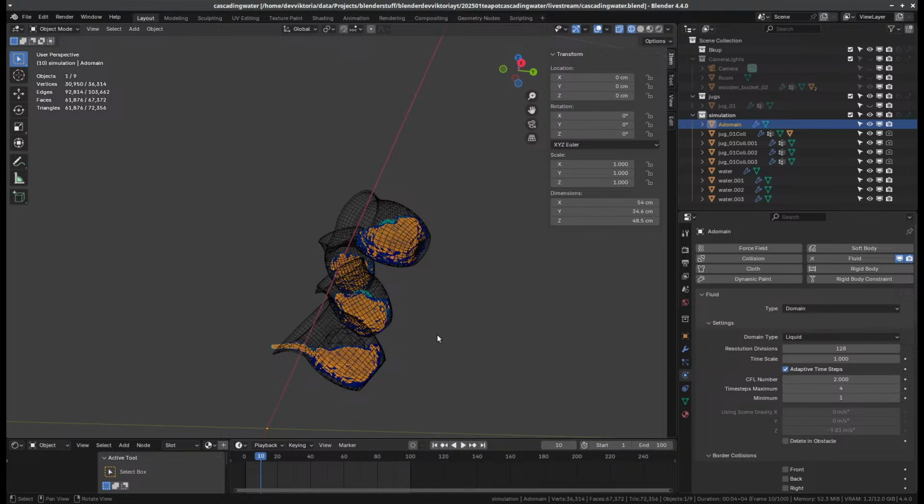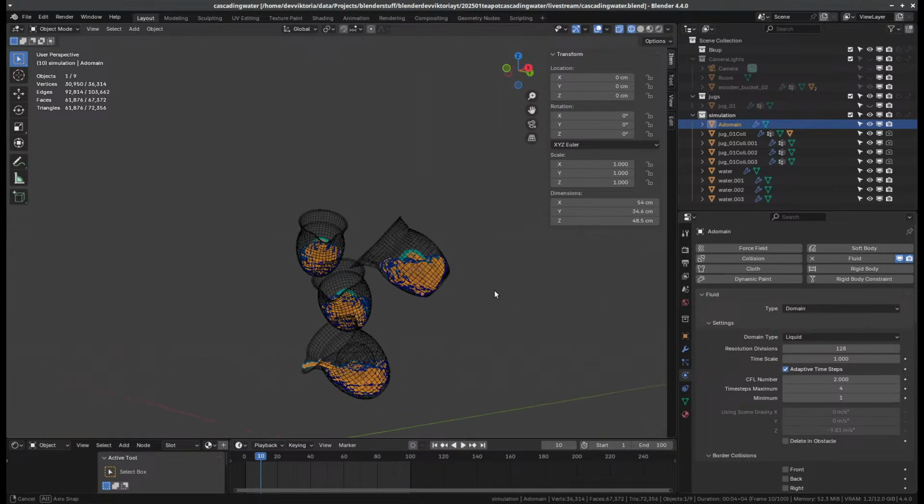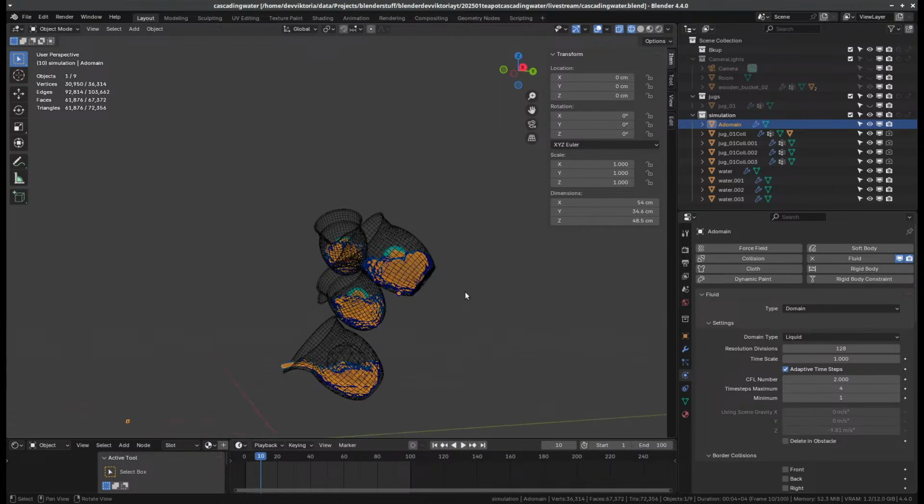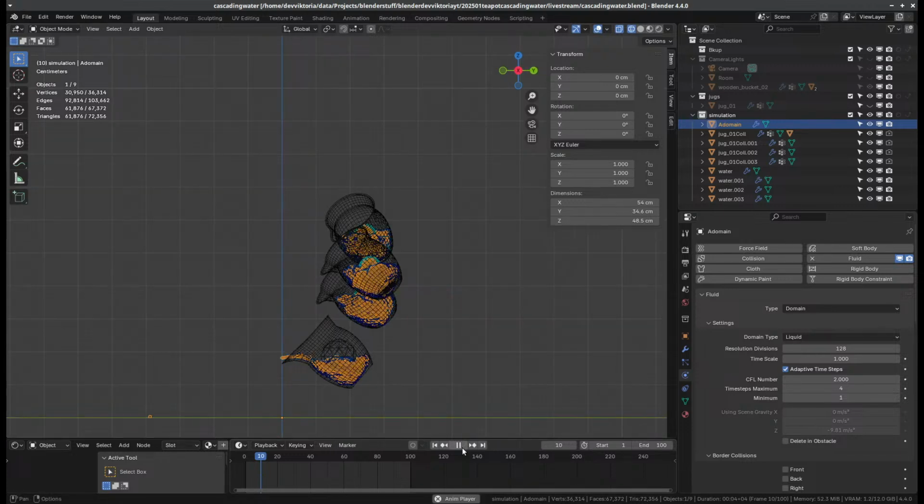Okay, let's pause the simulation. Let's go to side view or maybe, oh, well, maybe like so. Yeah, the domain resolution is quite big, but I think for this simulation, it's best to see with this resolution because the resolution is affecting the flow of the objects. Obviously, I'm going real scale, so lower resolution might not give the accurate results.